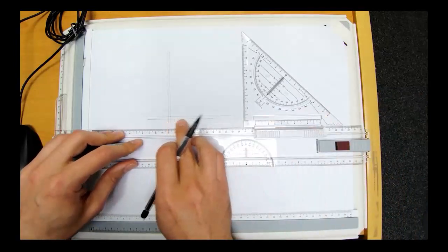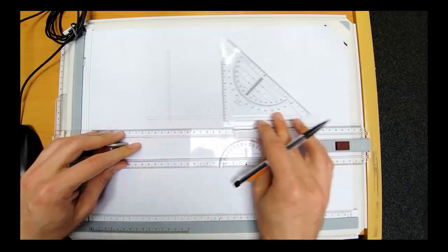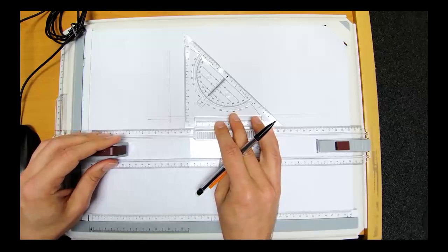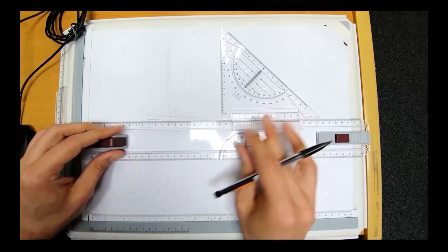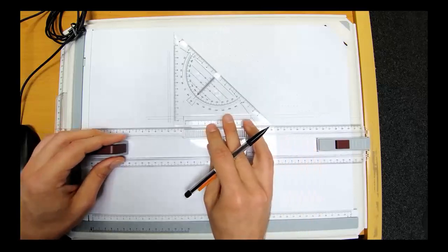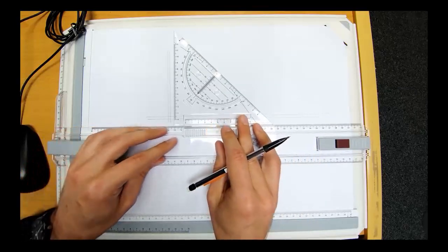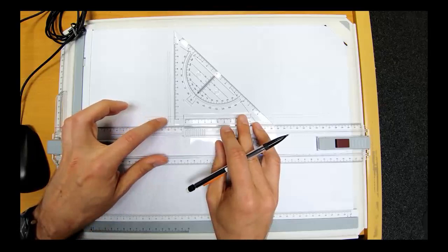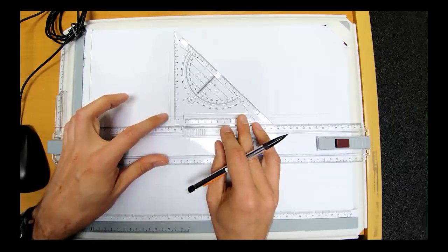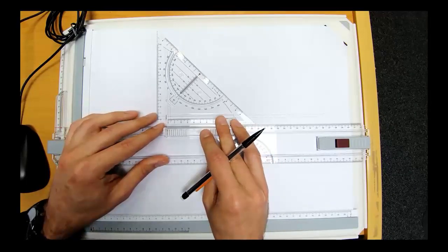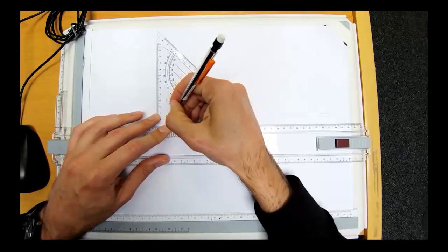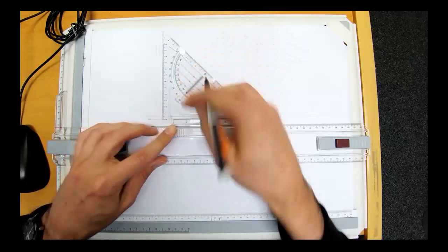Now I'm going to start with the door. There's an entrance door here. This entrance door is 300 millimeters from the external surface of the side wall. So this will be 6 millimeters on paper. Something like here.